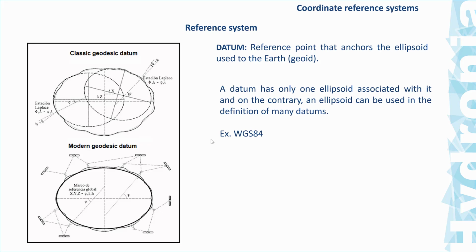We also need to use the datum. The datum is extremely important because there are many different standards or datums used in different areas, and even in a given area, there are some data that may be available in different datums. And it is important to know, if you are getting some data from a third party, what datum they are using,